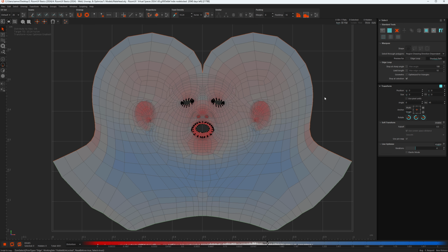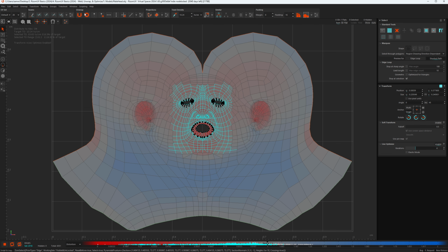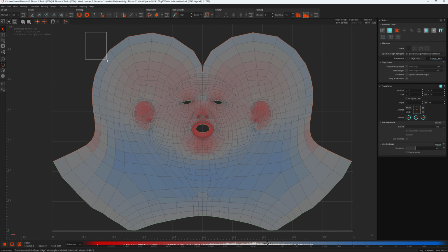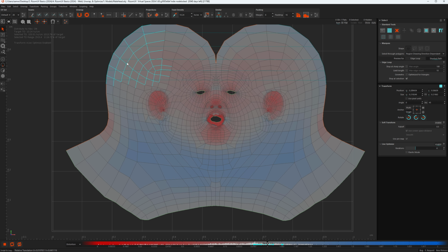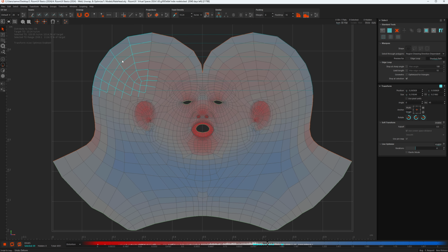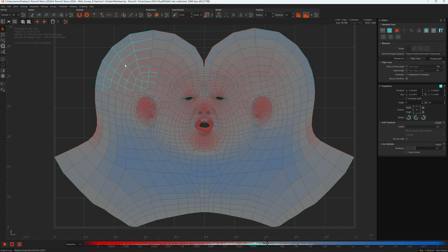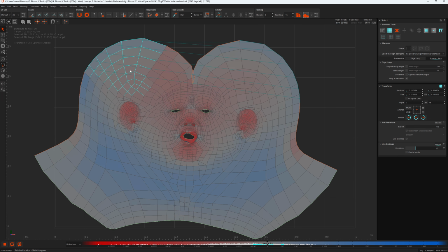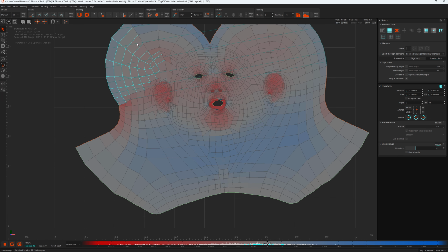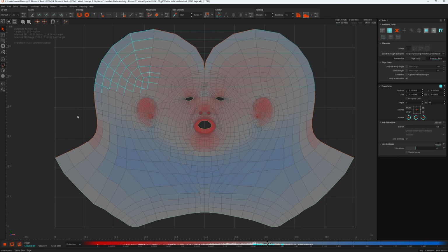Just going back to what I said earlier about the importance of having pinned points, let's unpin these points. So let's make an edge selection and unpin. And now we're going to make this selection again with Live Optimize enabled and move again. You can see that the entire island is coming along for the ride. And if I do the same thing with scale, it's not so bad, but with rotation the entire island is trying to come along too. Let's undo to get our pin back.